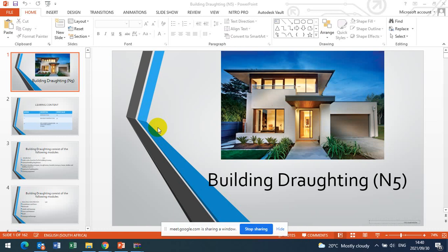Then the third question is a sectional elevation. A sectional elevation means you are cutting through the house in a vertical direction. You cut the house from the roof to the ground and throw away half of the house, the way we did sectioning last time on mechanical. You cut your house halfway across the house, not along the length, across the width. That's why we call it cross-sectional elevation. You cut across the house, throw one piece away, and then start looking at whatever you can see.